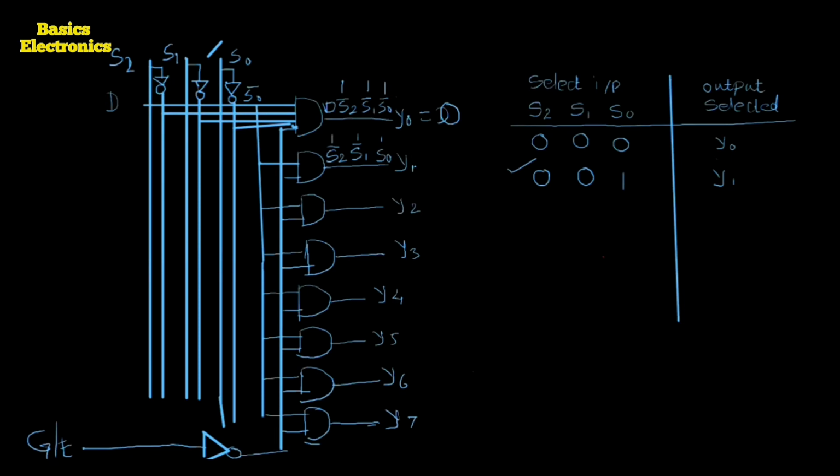So like that here we have to make the connection. For the second gate here we apply S2 bar. Okay, with me you apply the inputs, means you make the connections. I hope all of you made the connections before me. So here the S2 bar we apply. The first line is the S2 bar. Then the second line is the S1 bar. Here it is the S2 bar line.